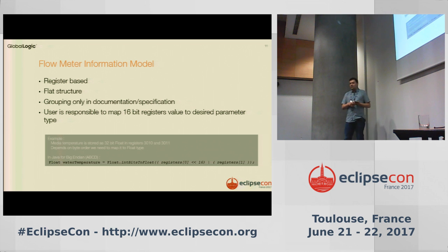For different protocols like HART, there is an electronic device description file which producers of such devices give with a device, and everything is described in a computer-understandable format and can be integrated into our solutions. But the HART specification is not open and there are no open source solutions, so it is hard to use it just for fun.